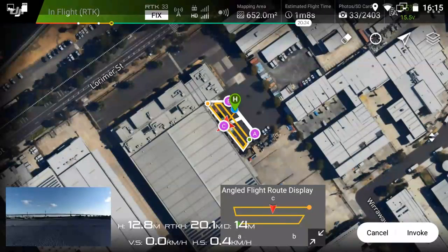So this example may not be pretty, but it gets the point across at least. So you just select point A and point B at the same heights, and then point C would be the top of whatever you're going to be mapping. This is super useful, say if you're in a mine site and you need to map the side of a wall or the slope that you're digging into, because it saves the risk of sending someone to a potential danger zone, and you can get a high quality map straight from the drone just by simply tapping, in this case, a couple of buttons.